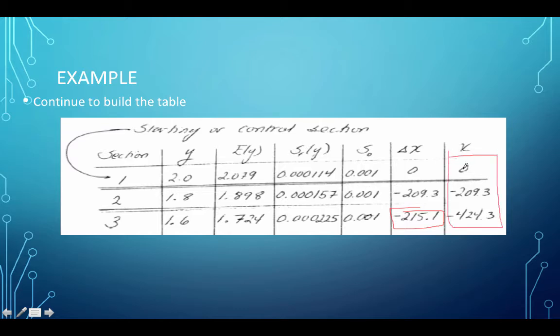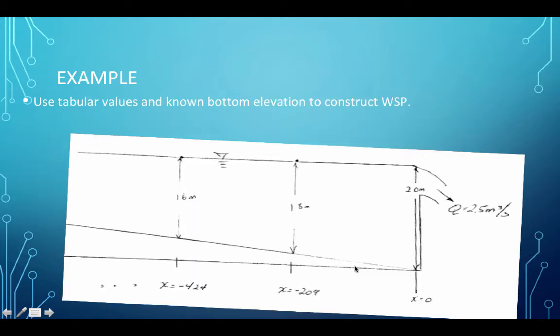That's our x position for section 1, x position for section 2, x position for section 3. We have the flow depths of those sections, and then if we actually kept track of the bottom depth, we could add the two and recover what the water surface profile looks like. Here this has been done, so there's a couple steps here, but these depths here have been added to those computed, those specified flow depths, and then the computed distances are shown here.